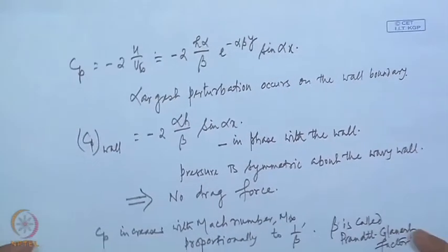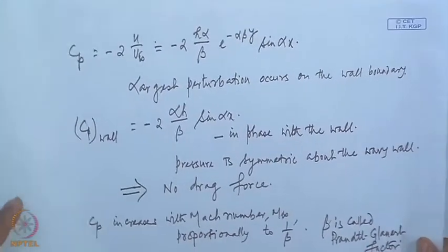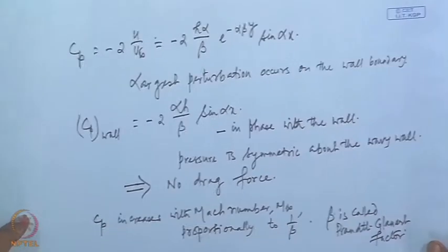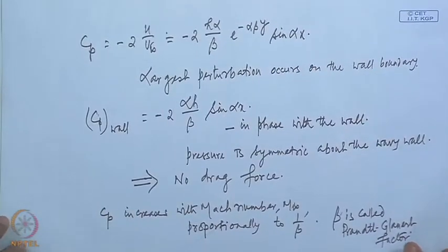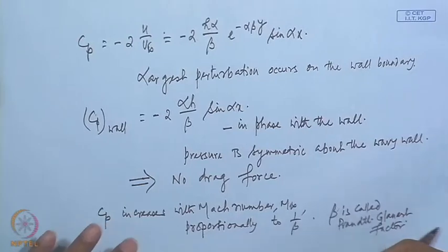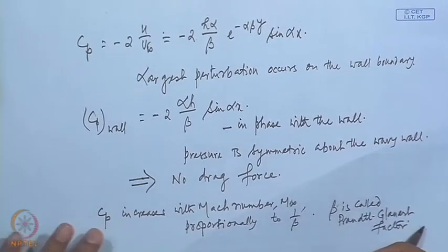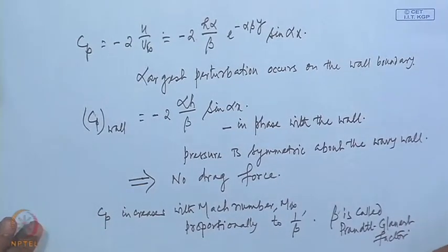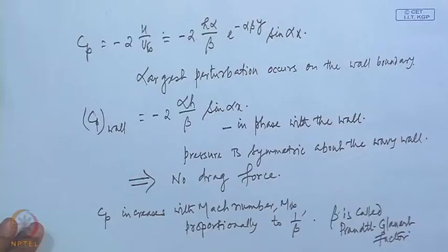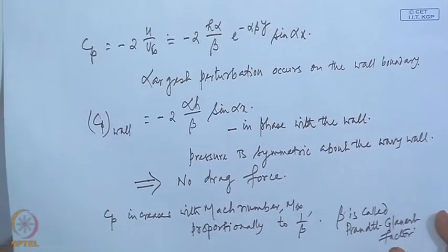So, in the limit of y approaching infinity, the perturbation velocities become 0, which again is a standard boundary condition used in incompressible flow, where the perturbation at infinity is 0. So, we see that we approach that situation in subsonic flow.